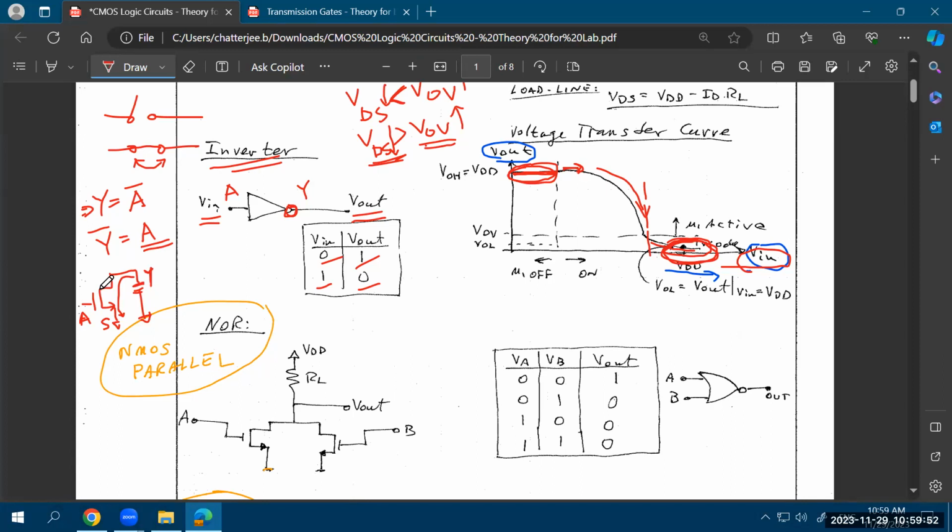So now you see why we put an NMOS over here: whenever the right-hand side of the function becomes 1, the output of the function becomes 0. That's why you try to design Y bar first. You are trying to design when the output of the function becomes 0. If you try to design Y, then you are trying to design when the output becomes 1. Y is equal to something: that means when that something becomes true, Y will become 1. Here, Y bar is equal to something: that means when that something is true, Y bar will become 1. In other words, Y will become 0. Right?